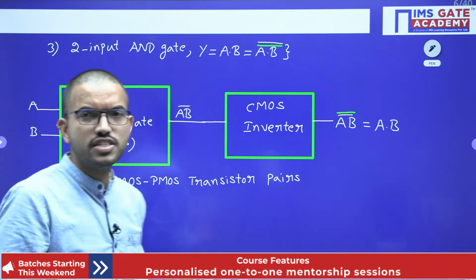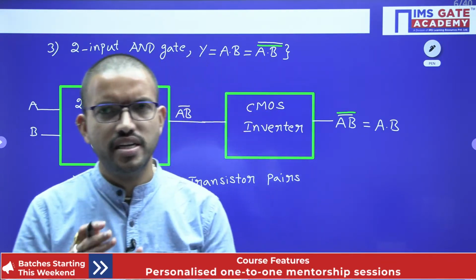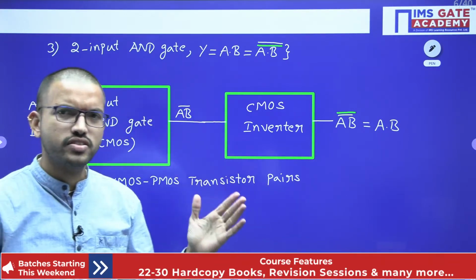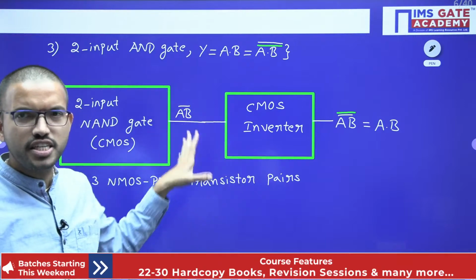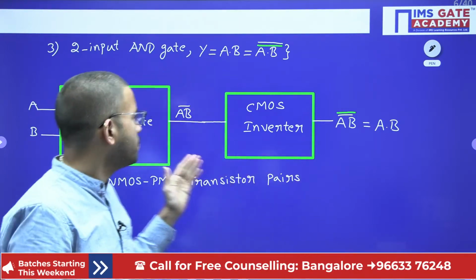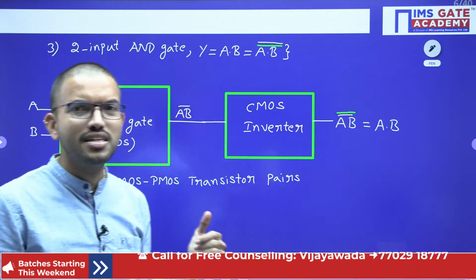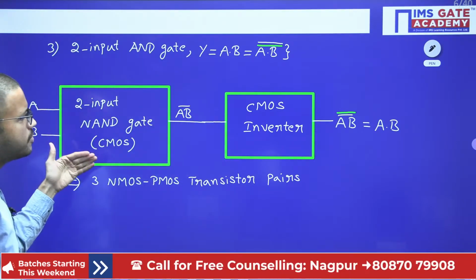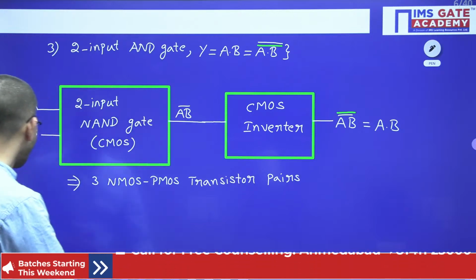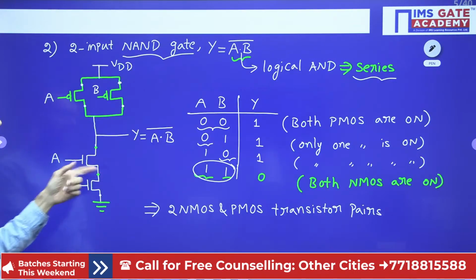In logic gates, when we studied, we discussed initially the AND gate, OR gate, NOT gate. Those 3 are the basic gates. Then we discussed the universal gates like NAND gate, NOR gate, and then special gates like XOR gate, XNOR gate. But in this particular session, instead of discussing the basic gates AND, OR, NOT in that flow, I have directly considered the NOT gate first. The reason is, in the CMOS logic, by default you get the output function in the complement version.